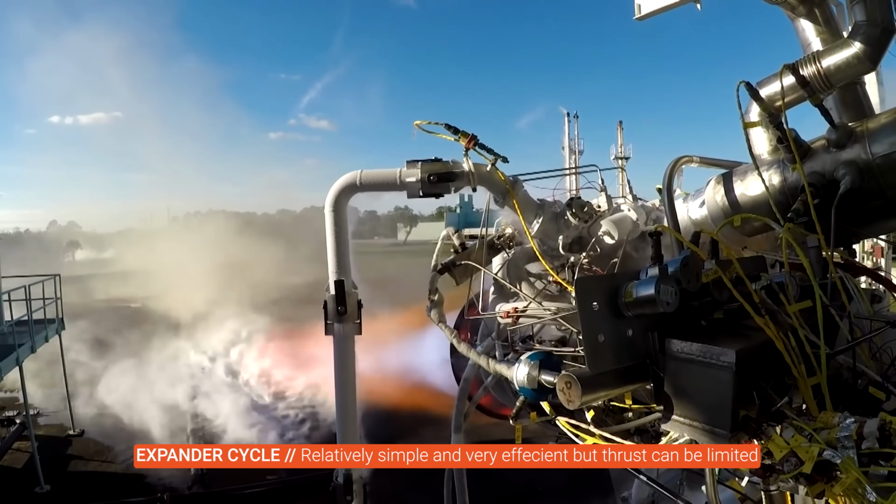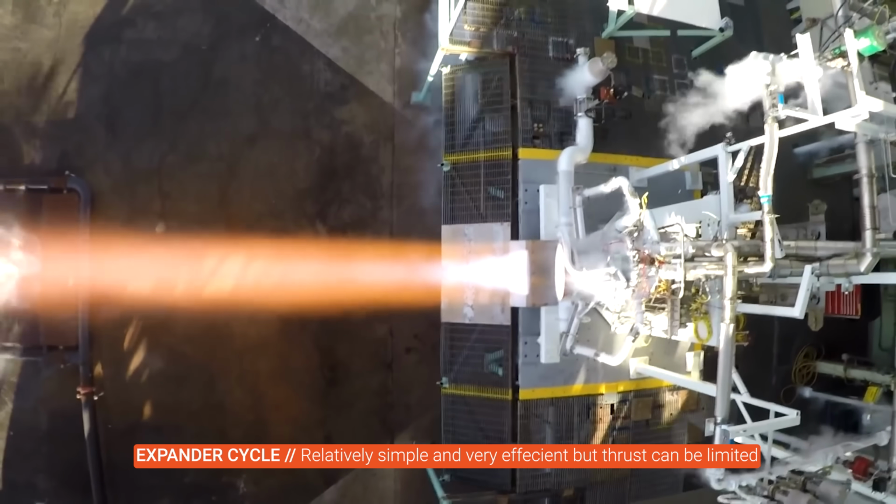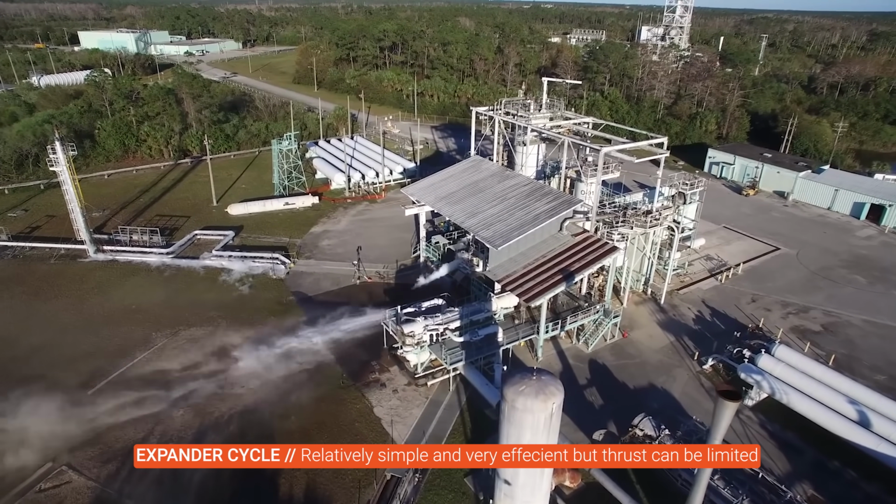Expander cycle is awesome, and has proven to be a great choice on the RL10, but it does have its limitations on thrust output, which often leaves it off the table for a booster engine. There are also a few options of mixing and matching cycle types, like using a gas generator on just the fuel side and the expander cycle to power the oxidizer side, or some unique combinations that engineers have come up with but haven't really seen the light of day yet. But yeah, that's how you power a rocket engine.